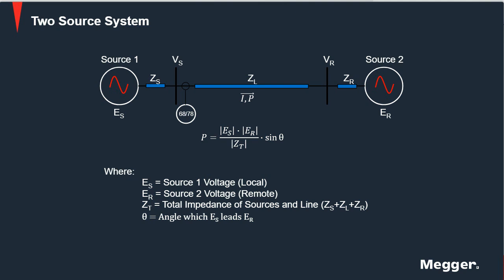When those oscillations are damped and let the system go back into a normal operating condition, albeit in a different operating point, then we call that a stable power swing. And when the system cannot recover from those conditions, then we call that an unstable power swing.